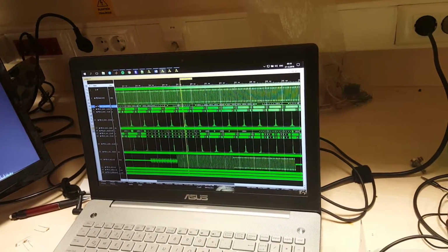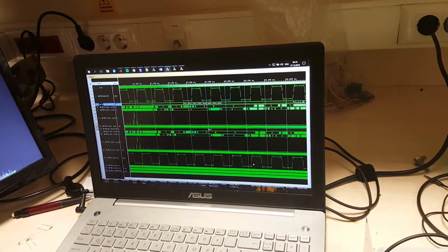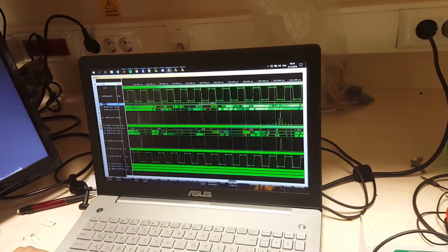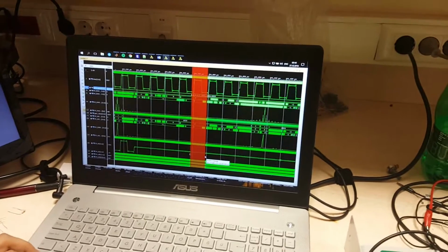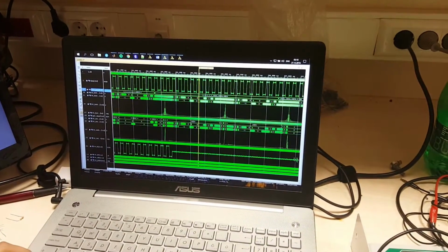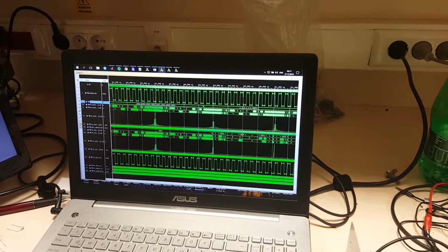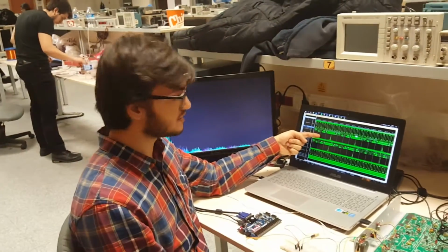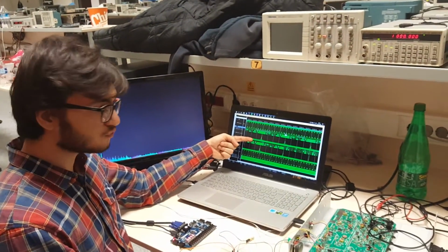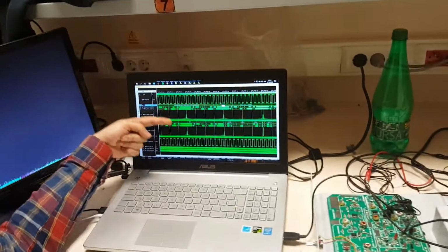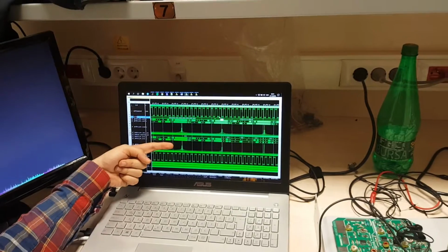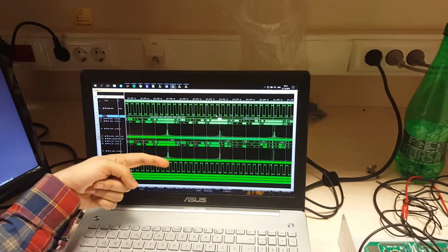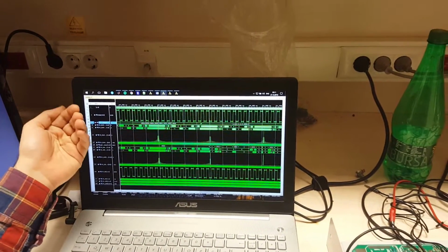And it goes like this. I apply different filters. For example, this is an all pass filter. I get the original input signal. And then I apply different filters again. But the important thing is that the filtering procedure is done in the frequency domain. So I first take the forward Fourier transform of my signal and then apply a transfer function to it by multiplying with a transfer function, and then I get a new frequency domain signal here, and then take an inverse Fourier transform to get an audible signal.